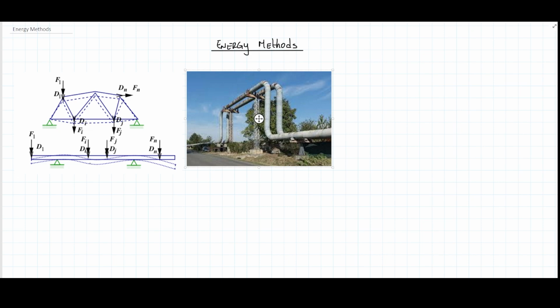Now, it is important to mention here that when we talk about strain, in comparison to deformation, strains can be smaller by several orders of magnitude. When we talk about deriving the equations for stress under certain circumstances, remember that we also consider that strain happens in a very small, very reduced way, meaning that it's not large in comparison with the dimension of the whole structure or element we are analyzing.